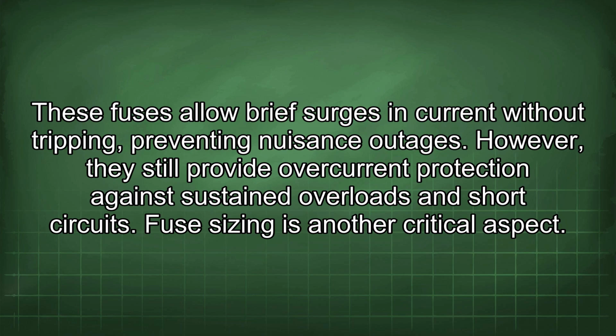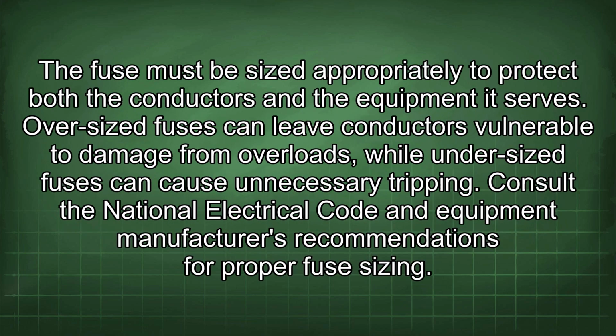Fuse sizing is another critical aspect. The fuse must be sized appropriately to protect both the conductors and the equipment it serves. Oversized fuses can leave conductors vulnerable to damage from overloads, while undersized fuses can cause unnecessary tripping. Consult the National Electrical Code and equipment manufacturers' recommendations for proper fuse sizing.